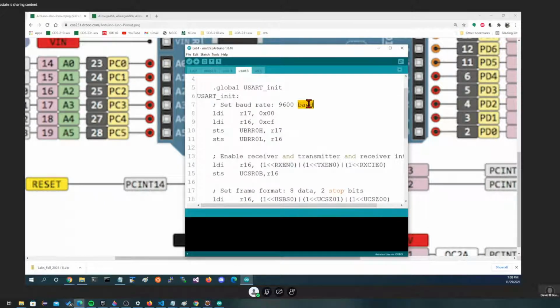Baud is an old word which was meant on old machines, how often it changed per second. Bits per second is real. It means how many bits per second we need. Baud is really a method of telling us how many electrical changes there are per second, from which we derive bits per second. Because we might have a baud rate which is half the speed of our bits per second, because it has 4 levels it can transmit at, 0 0, 0 1, 1 0, and 1 1, meaning we could have 4 levels transmitted in 2 bits. So we use baud rate in ASCII terms, but we mean bits per second.